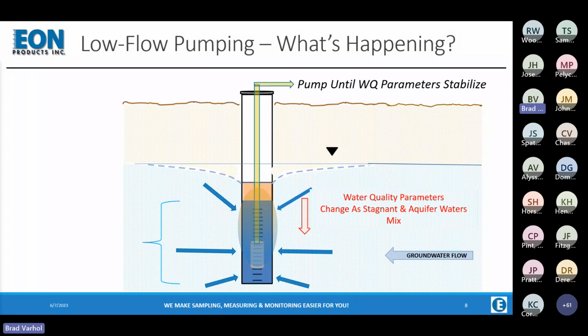One other thing that we've learned from the USGS is that as we pump low flow sampling, over time, those flow lines become very similar to those of a high pumped well, and that what ultimately we're representing is a flow weighted average across the screen. And by flow weighted, we mean that we have more contribution from higher hydraulic conductivity, higher permeability areas, and lower contribution from tight areas, if you want to call it that, but it's a blend over the length of the screen.